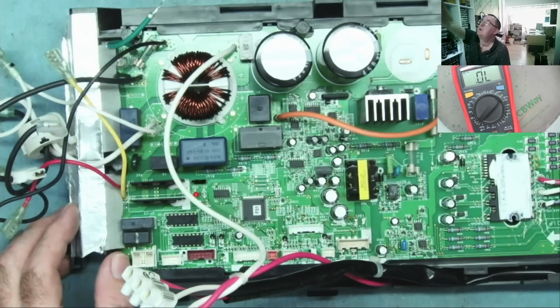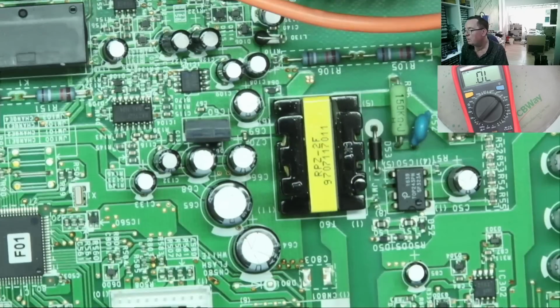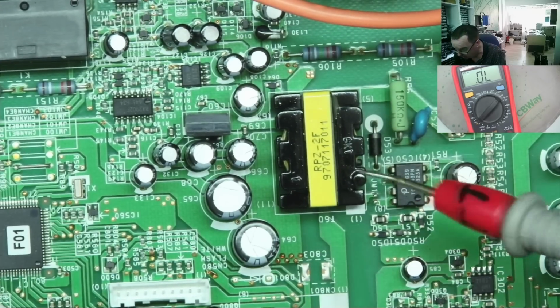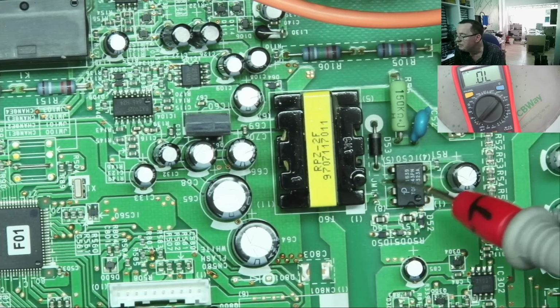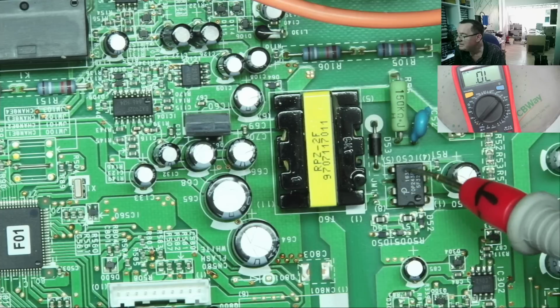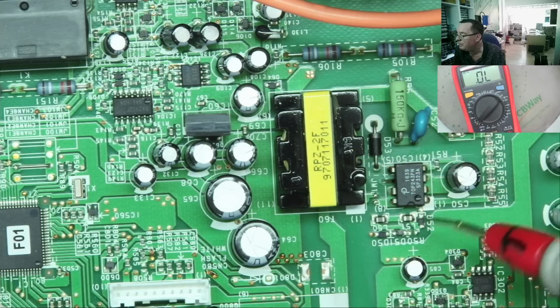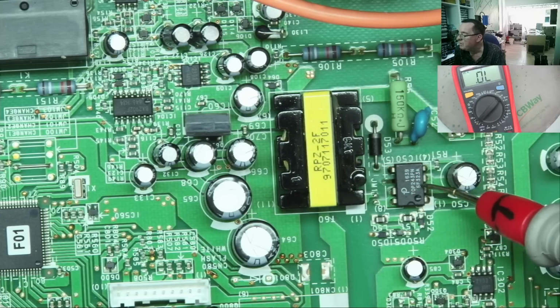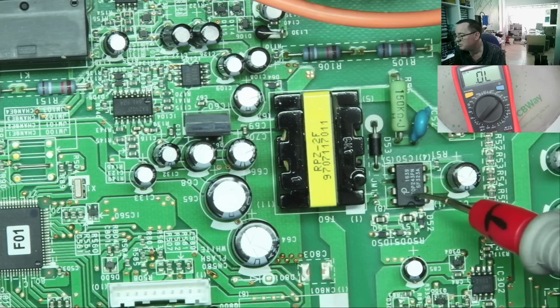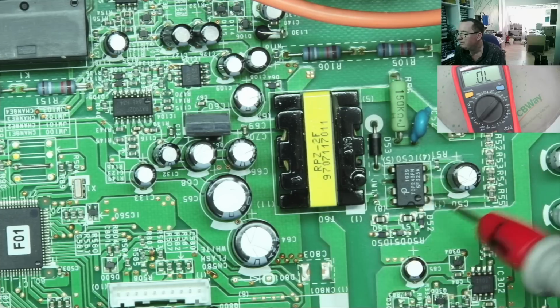This is a switch mode power supply again, quite obvious, a low powered one. So the reason it's quite obvious, you see the missing pin there. This is the high voltage pin, this is the transformer. These TOP whatever chips, these are switch mode controllers basically, at least the ones I've seen.